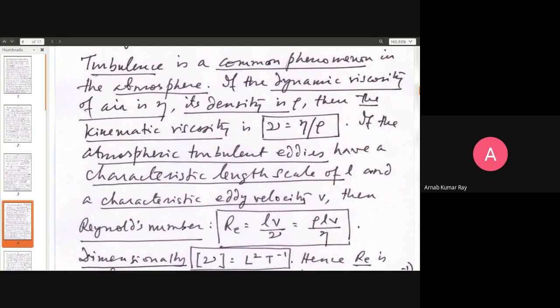Now, diffusion is an inherent property of the fluid material, right? Certain fluid material will allow faster diffusion, certain will allow slower diffusion. It depends on the density of the fluid, the molecular structure of the molecules, all those things. But it's still an inherent property of the fluid. But you are enhancing diffusion by creating turbulence or heating up. Heating will also create turbulence, right?